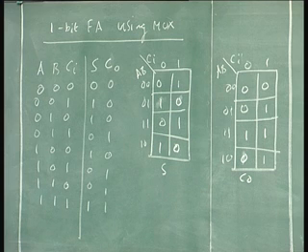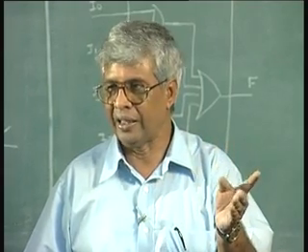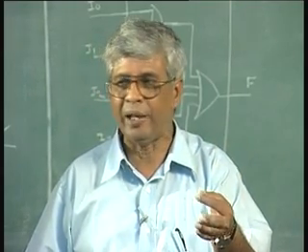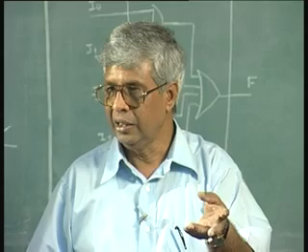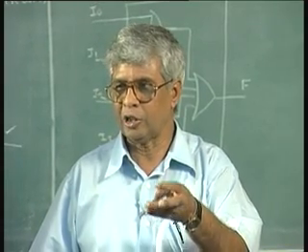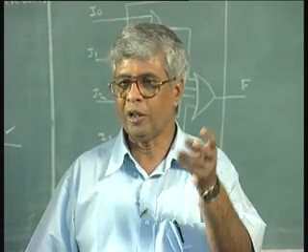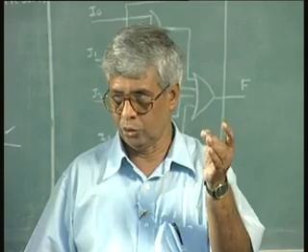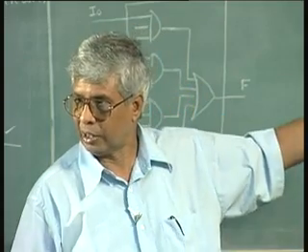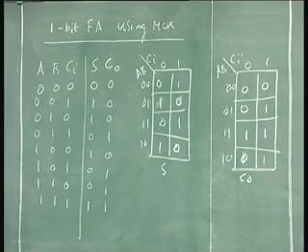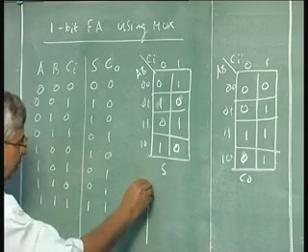I would like to use a 4 to 1 multiplexer. I need to select 2 of these variables as selectors. I have 3 variables A, B and Ci. Out of these, I need to select 2 of them as selector variables, and when these selector variables are 0, 0, what should be given as Ci, so that the output is what is required according to the table. So, what I am going to do is use a 4 to 1 multiplexer.